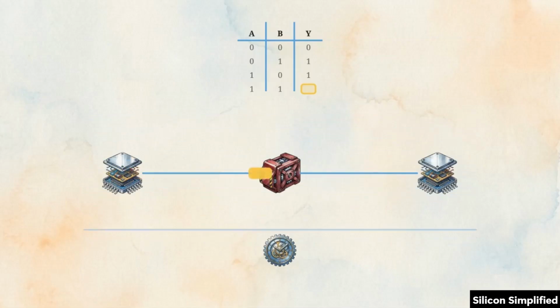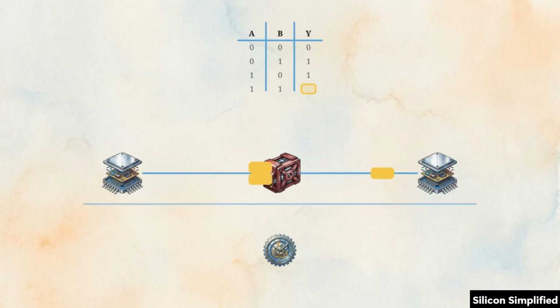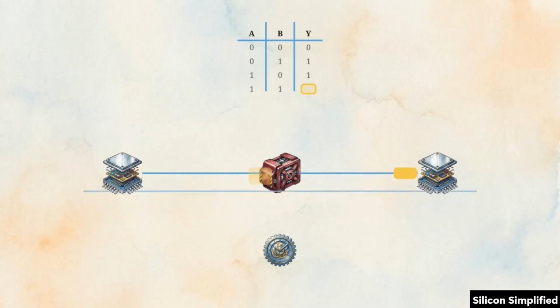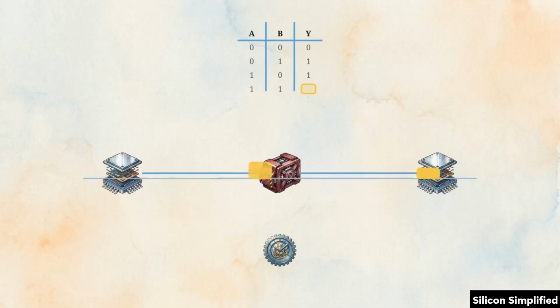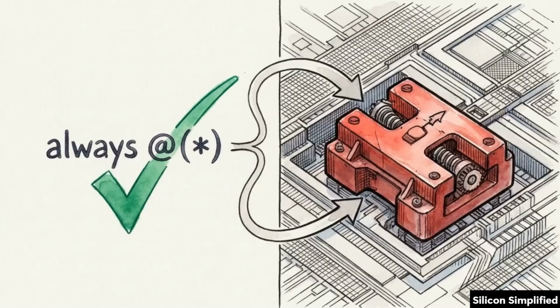In high-speed synchronous pipelines, this hidden latch is highly problematic, introducing asynchronous delays that disrupt timing closure and cause data collisions between synchronized flip-flops. The legacy always block accepts this code without issue. It compiles the error, never warning the designer that their combinational block now contains memory elements.